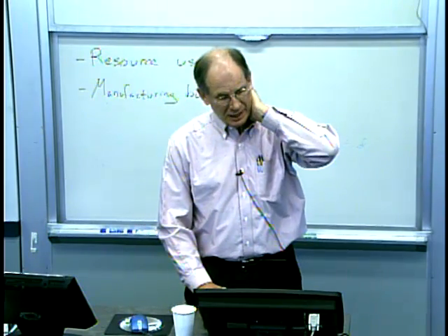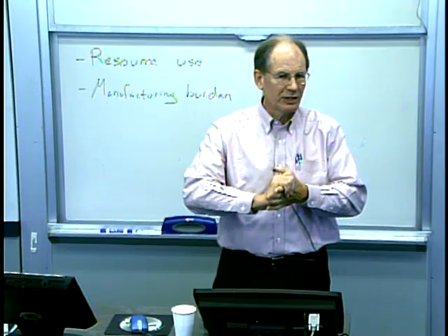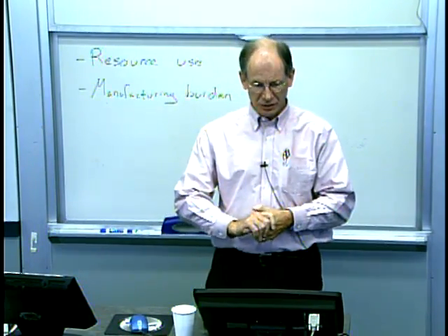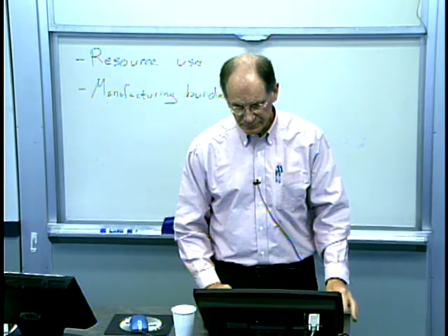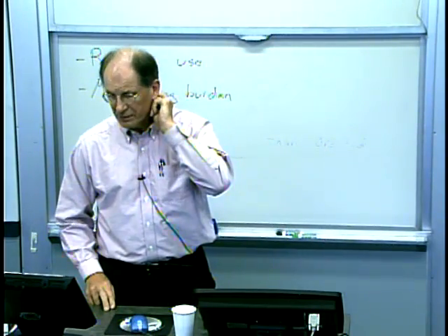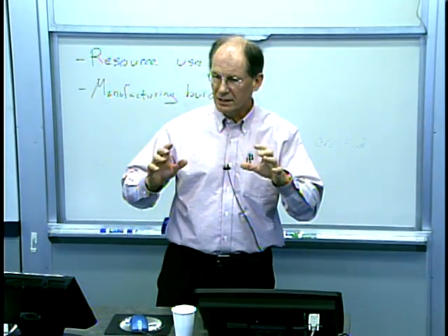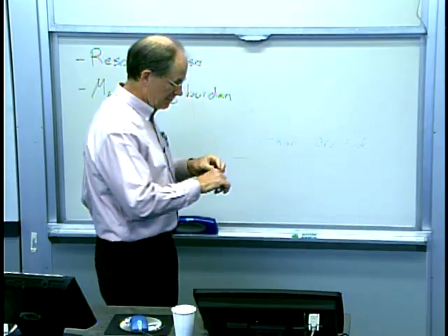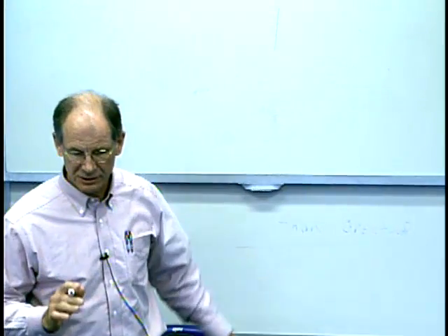And this idea of assignable causes, which, if you're from a control systems background, would be disturbances or changes, if they've all been eliminated, then it is a purely random process. So this concept of common causes, or again, purely random effects, if that's all that's left, then you do indeed have a process that is in a state of statistical control.